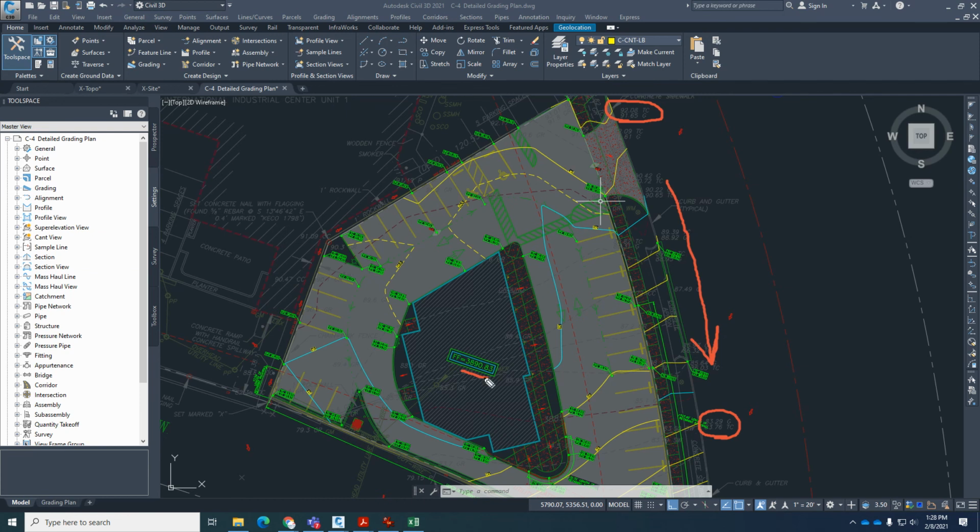So because of that, the engineer decided to kind of put it more or less in the middle, where it's nice and accessible. If you drive off the roadway here, you're not having to climb or drop in elevation, anything crazy. It's just very comfortable, and you're able to park your car here. This one is 89, 88 elevation. You're going to go from an 88 elevation up to a 90, so you're only climbing about 2 feet. So it's nice and comfortable.